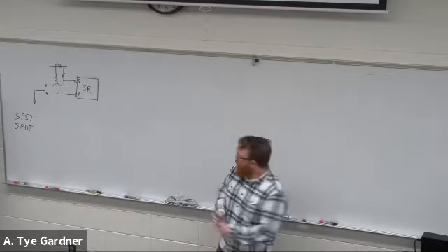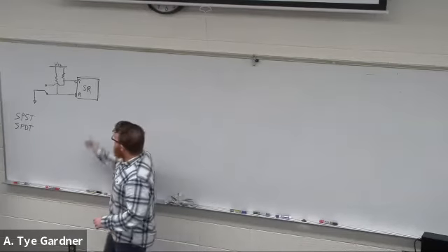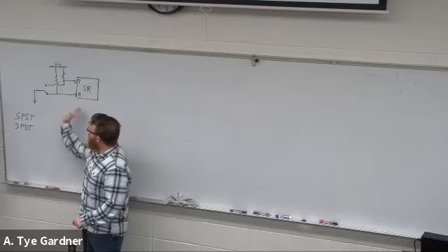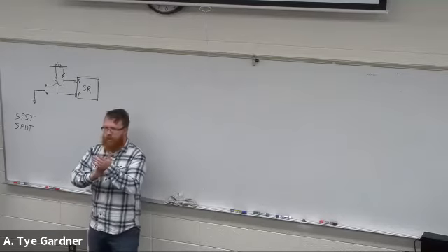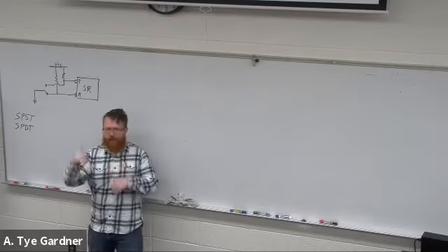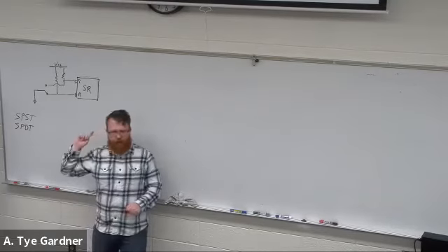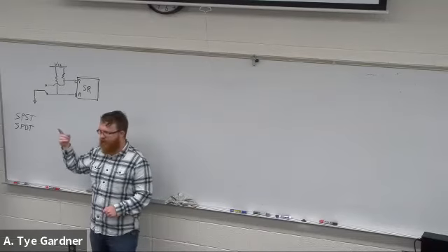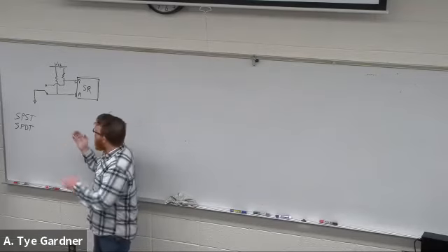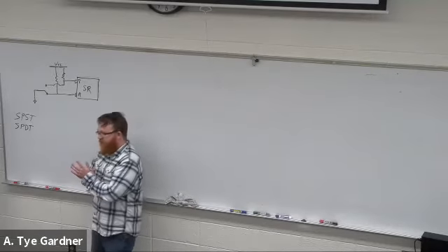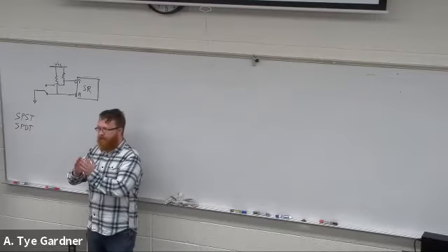So what's happening then is I push set, I want to go from 0 to 1, it goes and hits set. It does set, because an SR latch is combinational logic. It's not looking at any clock, it's not doing anything, everything's fine. So it goes and hits, it sets, it bounces off of that.